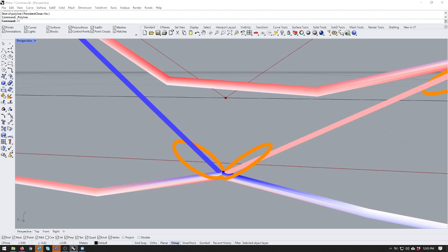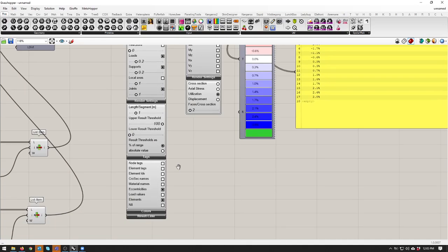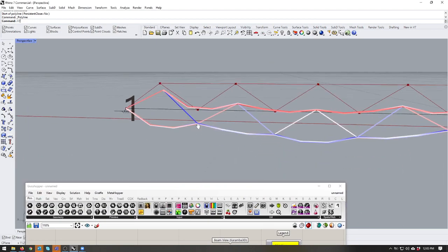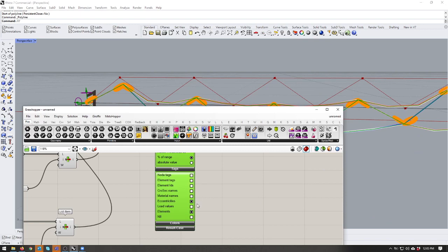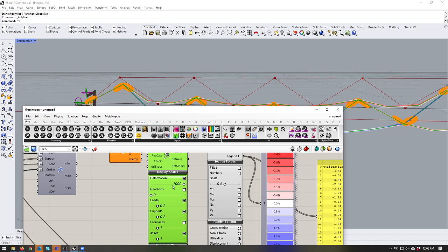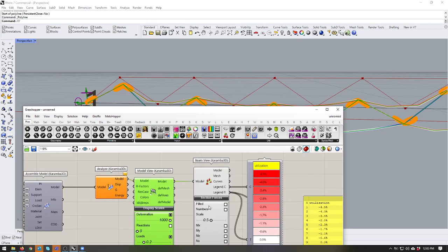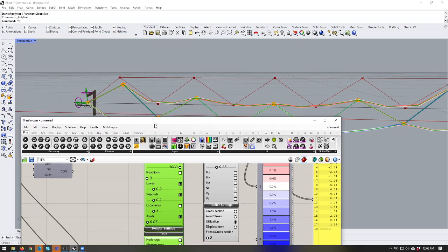If these are distracting you, you can turn off the model view, and they won't be shown. Or as well, in the model view, you can actually turn on and off things through here. Like you can change its size. Where's its scale? Is it this one? No. Joints. There we go. The joint scale. So that one, you can shrink them if they're getting a bit too big.